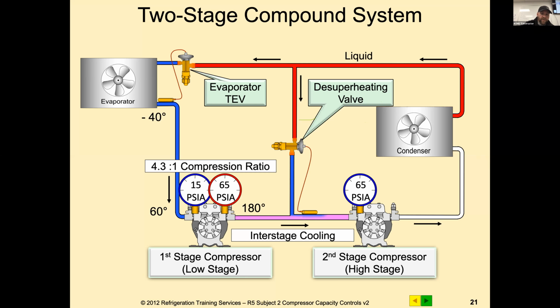So what it's going to do is meter in what we need to keep enough cool gas, based on that compressor's manufacturer spec. Make sure we keep a good close compression ratio. So 65 to 275, you see how the compression ratios are the same, about 4.3 to 1 and 4.2 to 1. That's healthy, right? That's good volume per stroke. If you try to take that negative 40 over to what the discharge is on this 180, that would be worse. It would actually be a lot higher than 180 also.